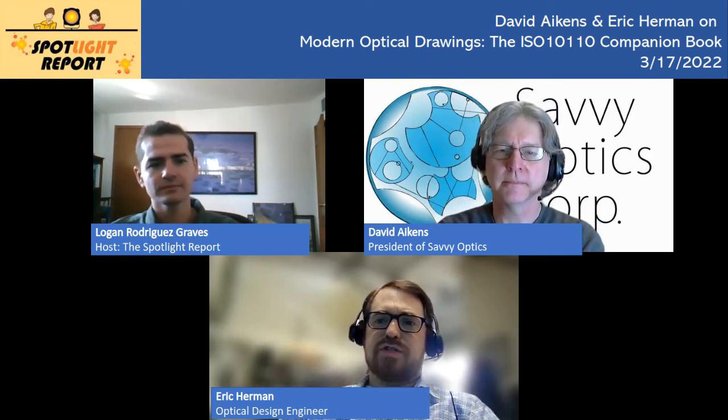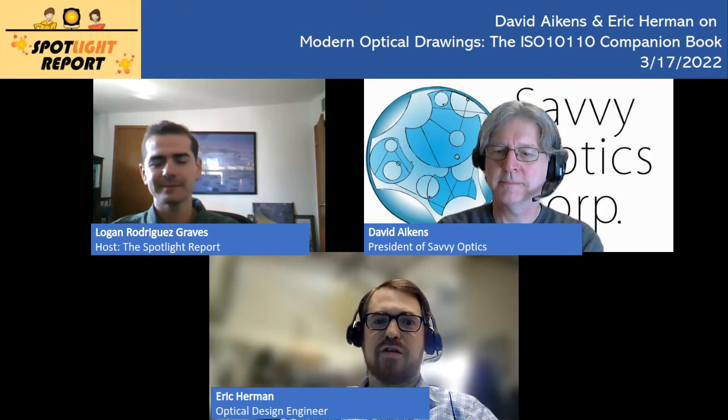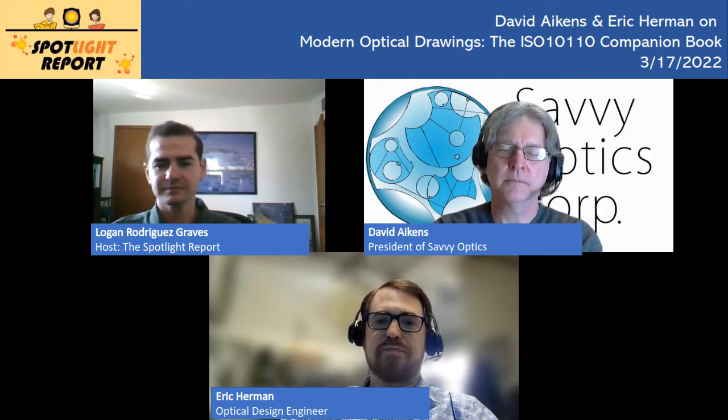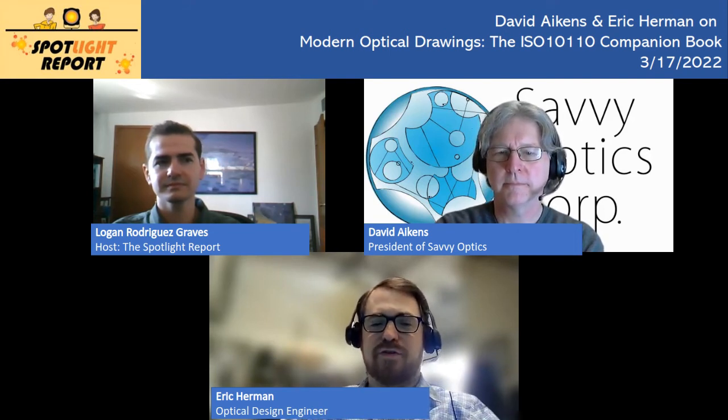We started with some base requirements that Dave, Richie, and I discussed. We had a design and said, okay, we want to make sure that we cover 3 different types of drawings. For the lens in question, we have a doublet, an asphere, and a normal singlet. Each of those 3 drawings is different in its own regard, because each one uses different aspects of ISO 10110 where others may not. And so taking each of those 3 parts, great, I now made my drawing for each one.